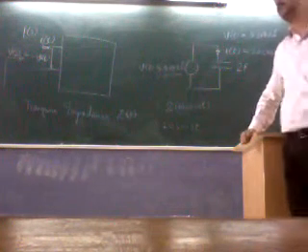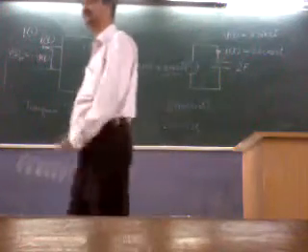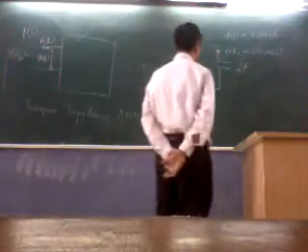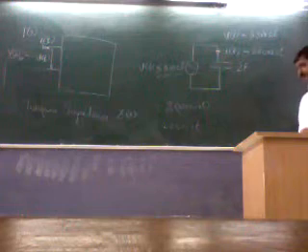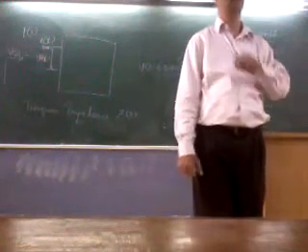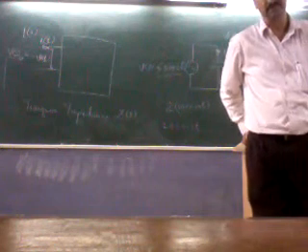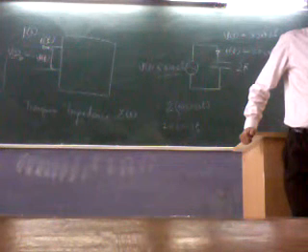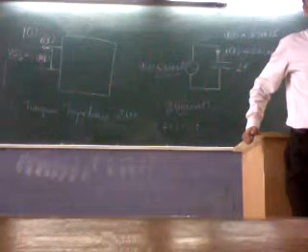And that means it can be anything. Time has the range from minus infinity to infinity. So substantially it defeats the very purpose of impedance, which is a term that describes a particular property: the relative relationship between V and I by a single figure. By a single figure is important. In that situation, defining this impedance to be tan 2t or 1/4 tan 2t defeats the purpose because it itself becomes a function. Then what is to be done?